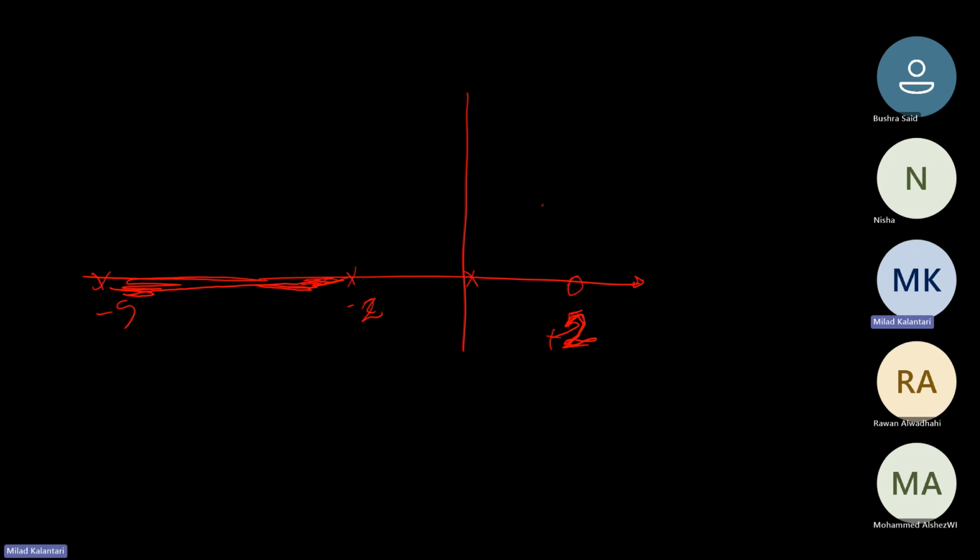I mean, I'm talking about this region. Is it possible to have the root locus to be here? It is possible, right? Because from here you actually have one pole or 0 at the right. So basically you have an odd number of poles or zeros. Then here, on the right side of you, you actually have an odd number of poles or zeros. You have 1, 0. So it's odd. So basically this region can be.